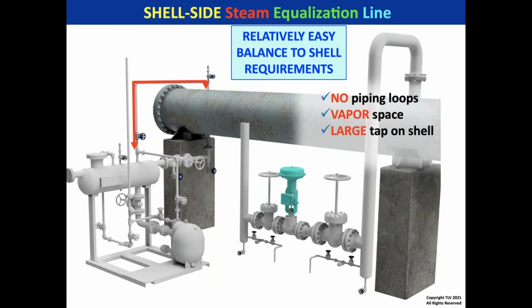When you're ordering new equipment, if you're not sure, why not just order with a 3-inch tap? You can always reduce that tapping down to 1-inch, but if it's a 1-inch tapping, it's so hard to get it up to a 3-inch tapping.